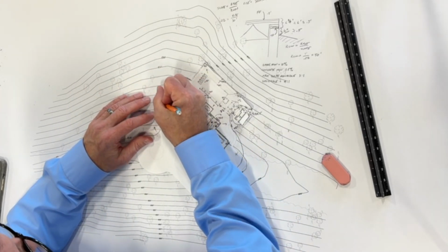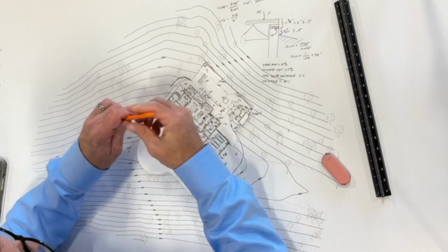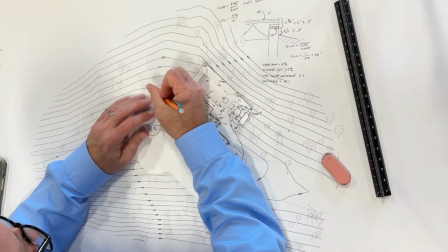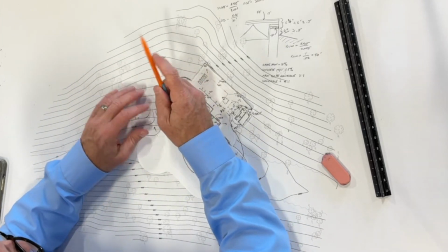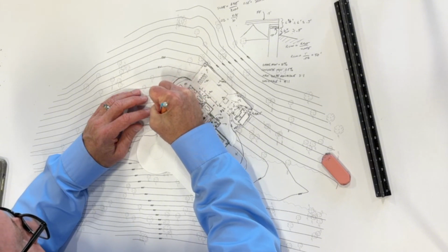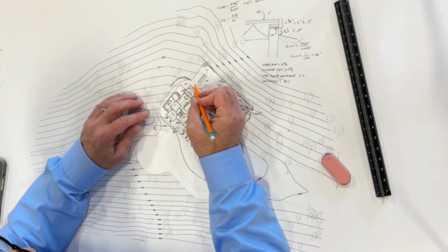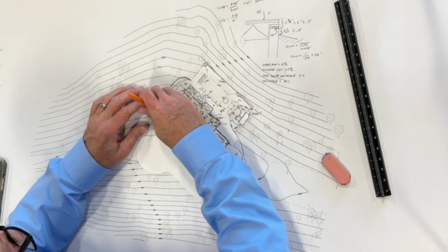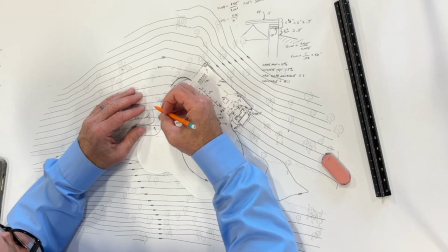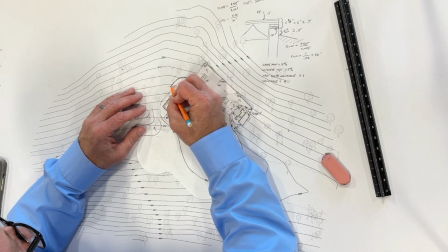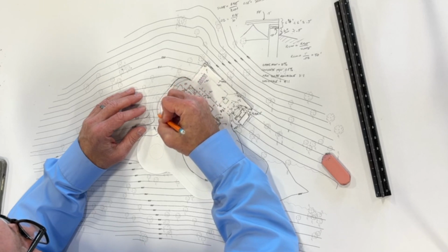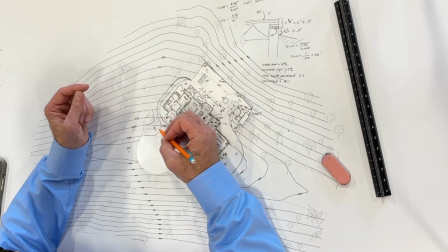Yeah, in fact, actually that's open space right there. So we can keep going, I can cross over where that area is there. So basically now we're going to have the ability to walk around the house to get to that door in the back area, which I think would be nice. And then we'll probably make one more contour be a little bit sloped but not bad, and that's going to catch the end of this retaining wall right here. So again, that's mowable. That's about a 4-to-1 to get to the 939.